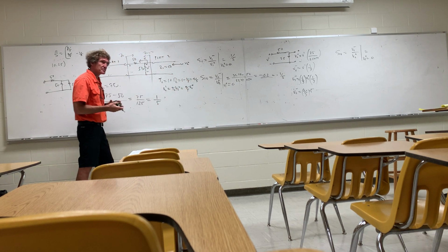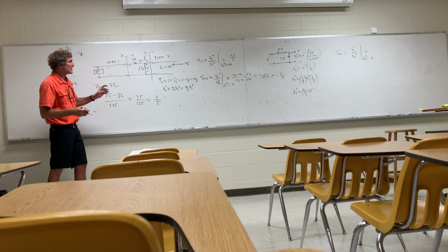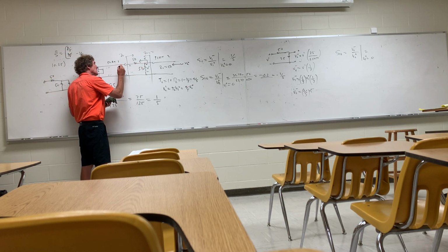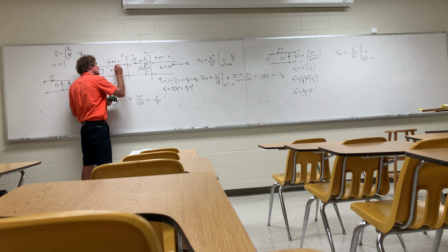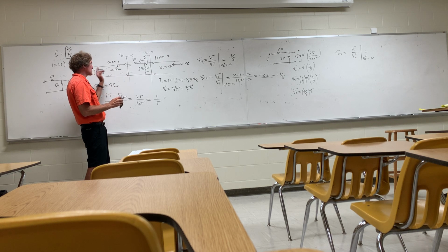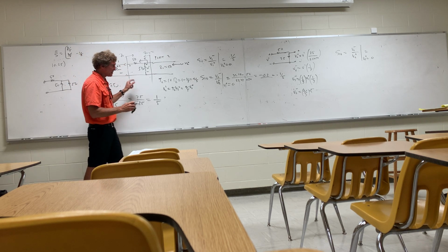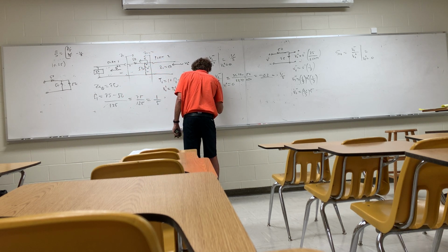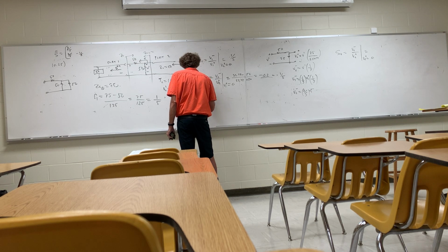Then what do I do? Now I've got the voltage here, but I need the voltage coming out, V1 minus. So how do I get that? Think what that network looks like in terms of just resistors. Can't I replace that transmission line, if it's matched, with just 50 ohms? So I've got this 50 ohm here, but I already know the V prime across it, in series with the transmission line, which looks like 50.